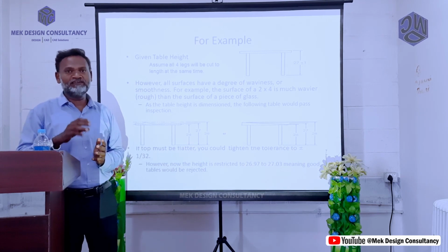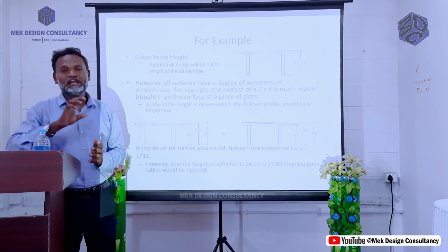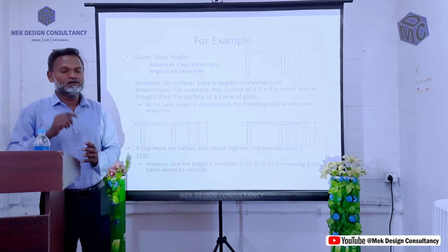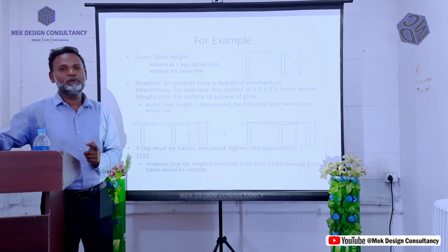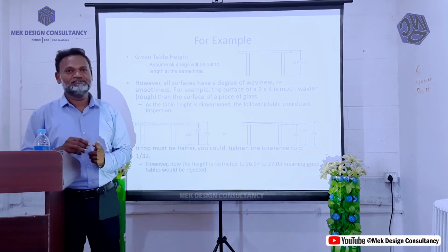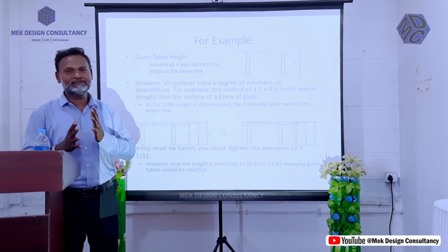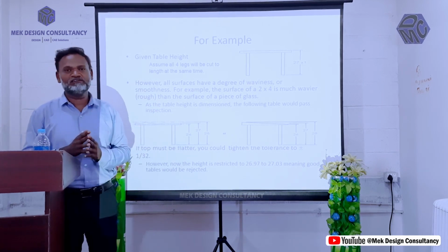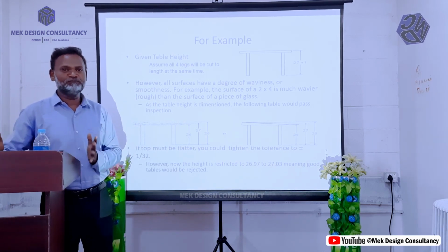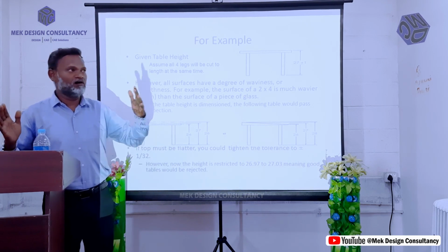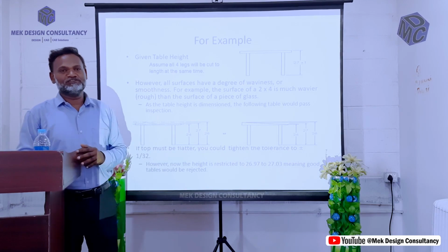They use those devices and check the dimensional parameters of the manufactured component. Right? The drawing, with the GD&T concepts and dimensions, should be matched with the product. So by using the inspection, they should validate whether the correct dimensions are there or not and whether tolerances are exactly specified or not. So that is the core concept: all three departments should be integrated for design.